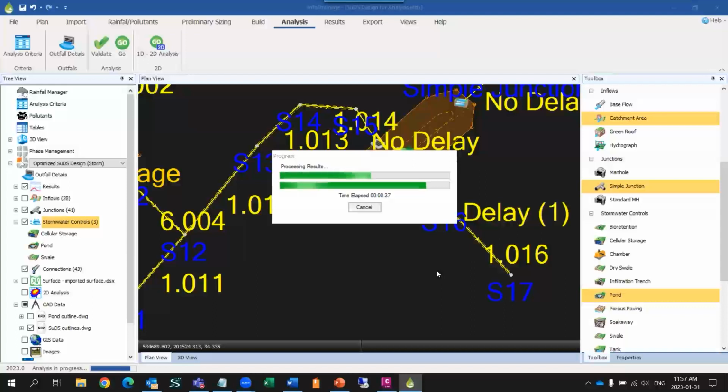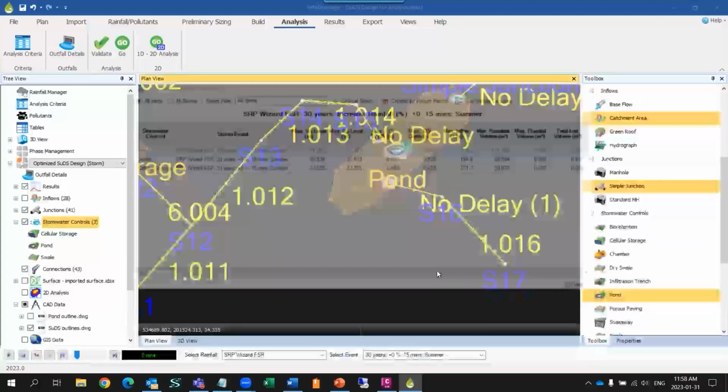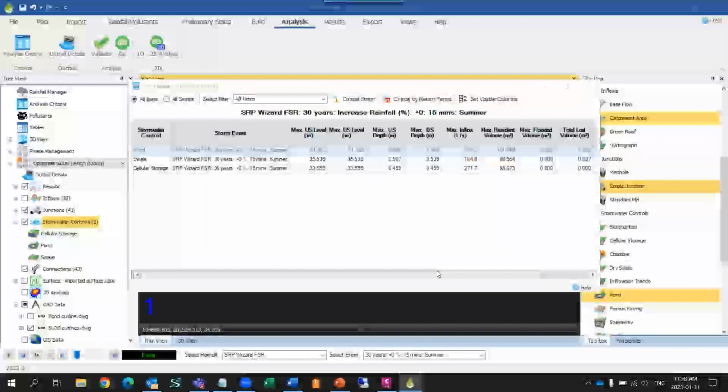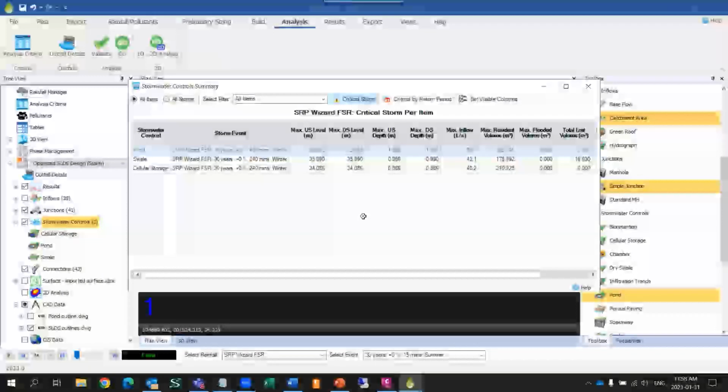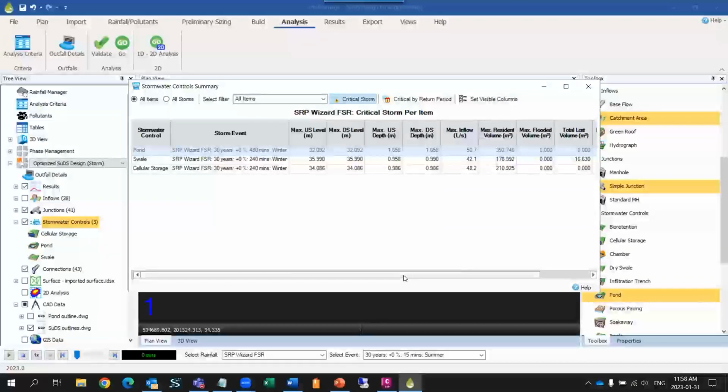So if you're designing a new subdivision, putting a set of pipes, need to run for analysis based on the available data, get the rainfall info, and then run it for like 5-year, 10-year, or 25-year, or even a once in a 100-year big storm scenario, and you will find a number of items and detailed challenges sometimes that need to be addressed when you're running all these multiple storms.